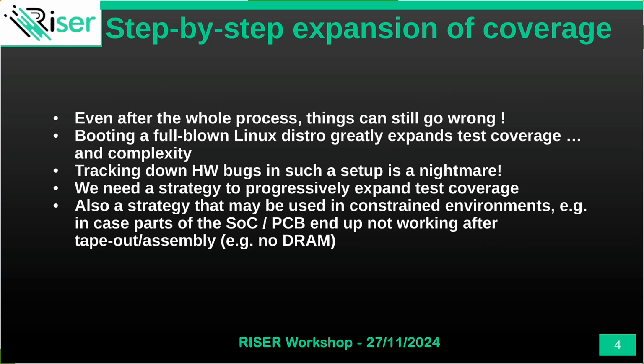Because now it's not in an FPGA anymore, it's an ASIC. You may have bugs in the process, you may have bugs in the PCB. So you need to also have tests to debug things after the tape out, and in many cases those tests are running in a very constrained environment.